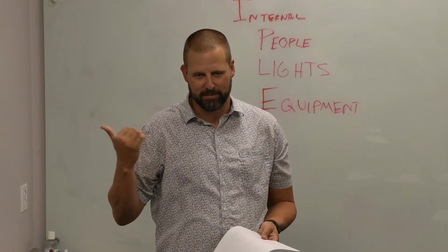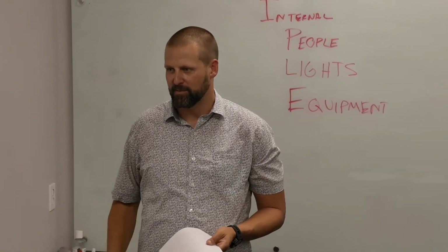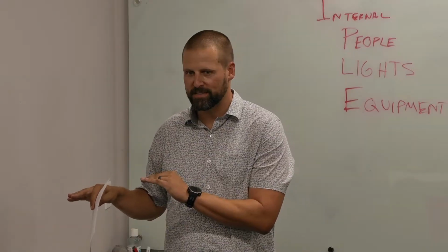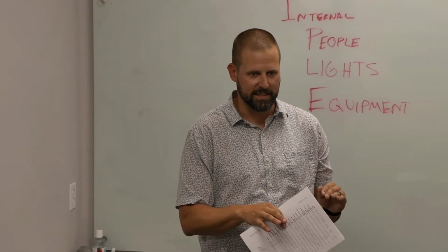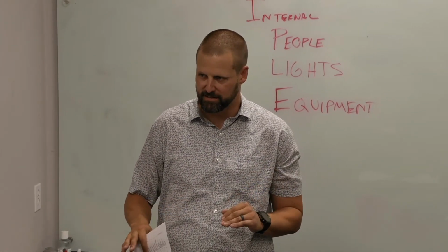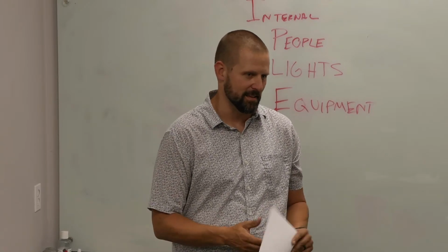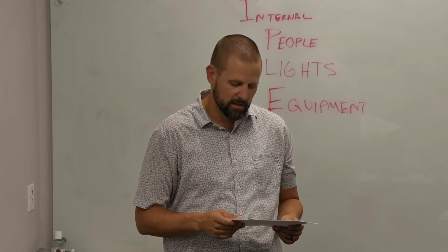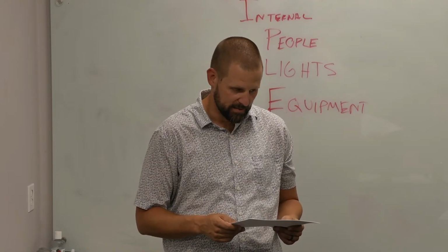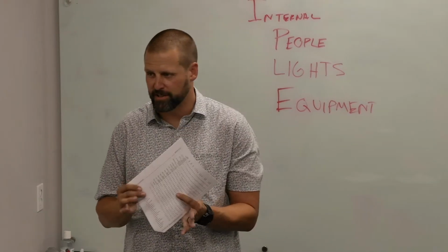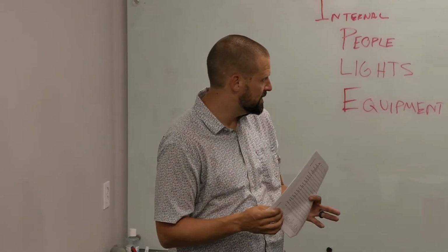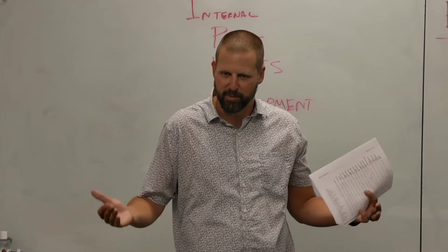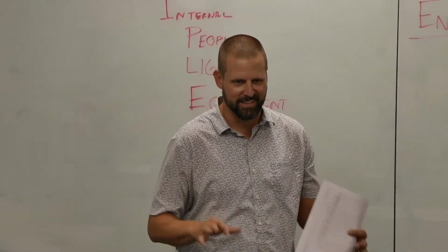South might have the same thing, or like Georgia, Atlanta, they have really hot, moist days. Generally, we design mostly to the sensible and don't worry too much about the latent. But that's another factor to think about, is how you deal with the humid days. Okay, we're gonna come back to this for heating, but right now we're not talking about heating. And we don't talk about heating a lot in the market, but we will today, so get excited.